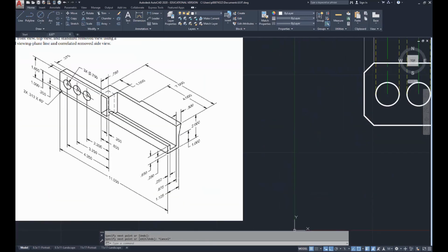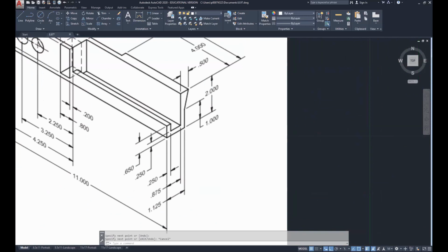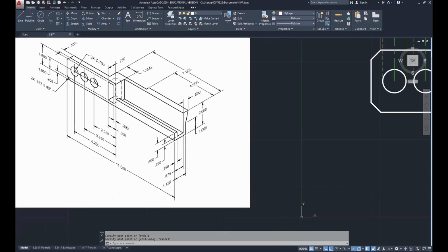And then I also have on this side 0.250, 0.875, and 1.125. This one is a little bit confusing for this side here. You'll see that it's 0.5, but it's coming from 0.5 from the 0.875. So I have to do a little bit of backtracking for that one. Be aware if they do dimensions like this, not to just assume that that's the total. The total is not dimensioned for this side view or top view. You have to do a little bit of math for that.